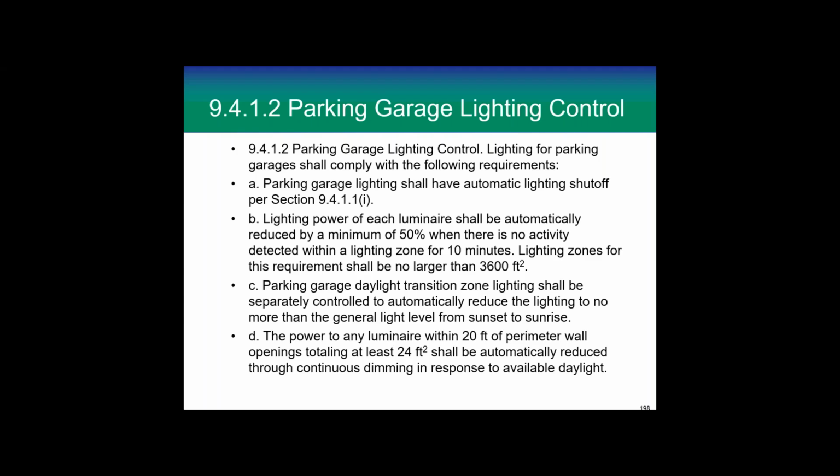Parking garage daylighting, transition zone lighting shall be separately controlled to automatically reduce the lighting to no more than the general lighting level from sunset to sunrise. So from when it gets dark outside, we want your eyes to dilate. Does that make sense? When it's bright daylight outside, you're coming out of a dark parking garage, and when you hit the street, you can't see because your eyes haven't adjusted to the daylight.